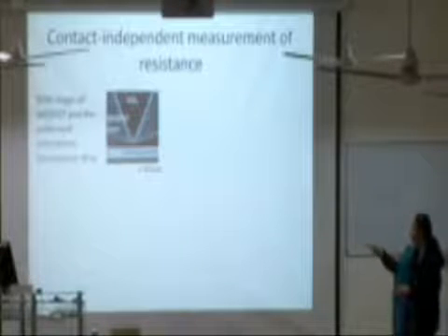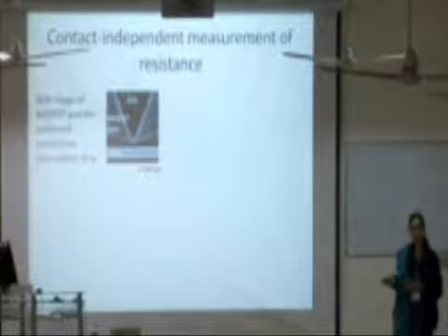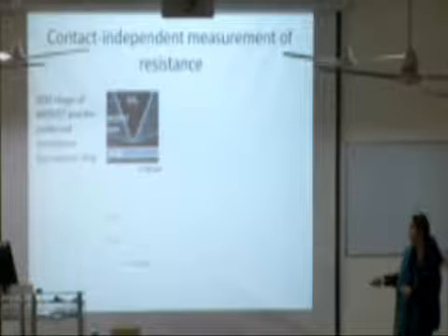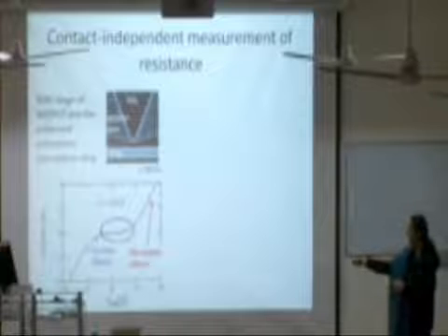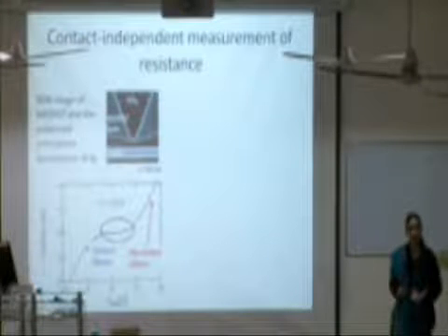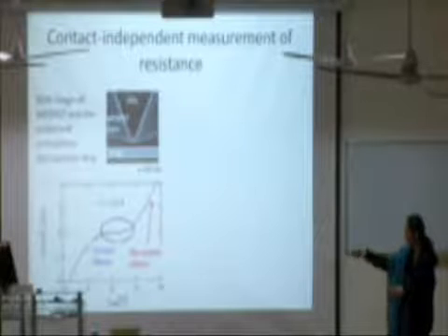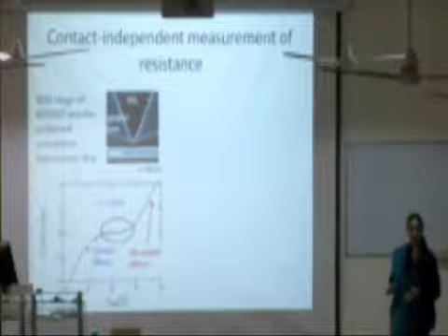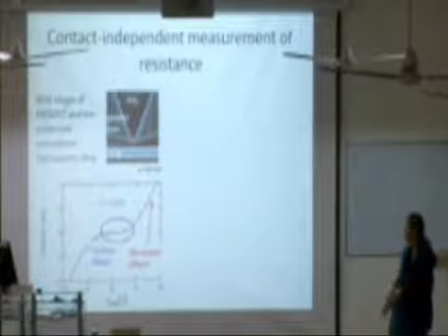Going back to the MOSFET gate and the amorphous germanium strip, let's first try to measure the current that comes out of the material. We measure the current as a function of voltage, and we see that at lower voltages, say below 5 volts, we can hardly measure any current coming out of the material. But as we go to higher voltages, we are no longer dominated by contact effects, and we start to see a current flowing out of the material.